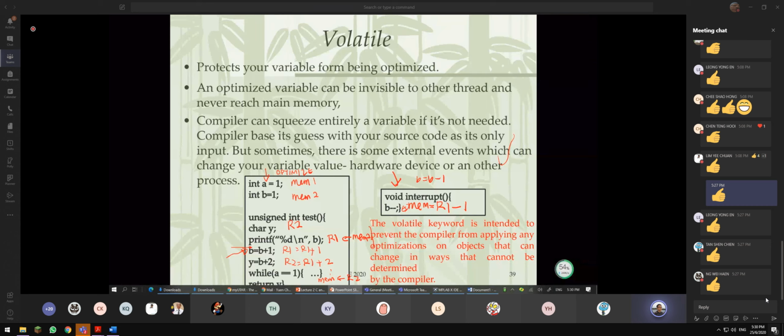So in this situation, error. This error is very, very serious. Why is it serious? Because you don't know when the interrupt occurs. So for a student, they will say sometimes can, sometimes cannot. Because if the interrupt didn't occur, it will work perfectly. You're so happy. If the interrupt occurs, why is it not working? And worse, you don't know when the interrupt occurs. So that's the reason it's very, very risky.